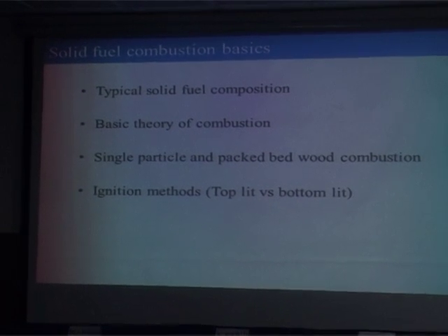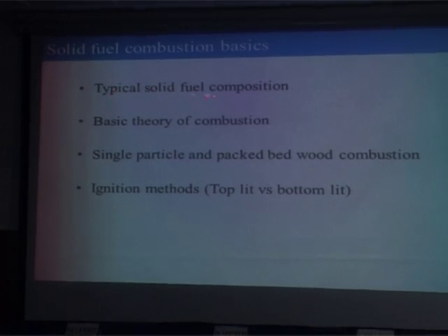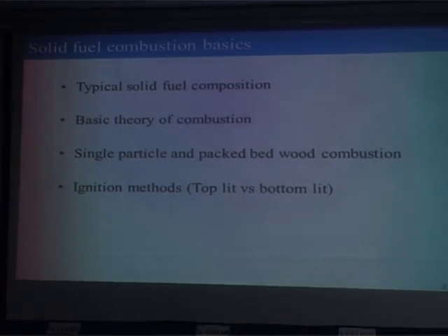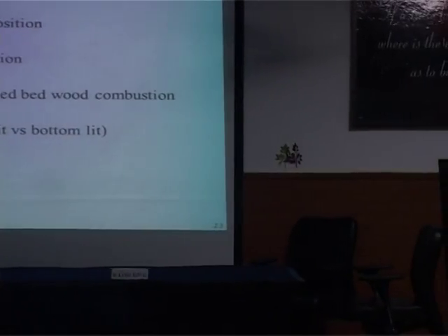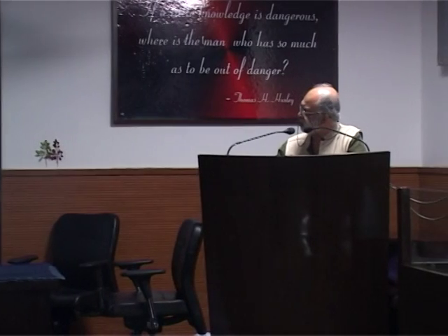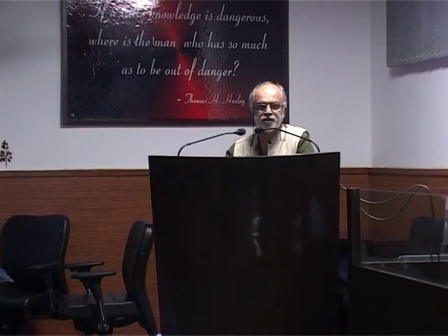So the basics of any solid combustion fuel device, typically we require a solid fuel composition. So from first principles, I can calculate the calorific value of that particular fuel. You would require approximate and ultimate analysis of the fuel. Then I need to understand the theory of combustion, which is essentially the oxidation reactions of various components which are